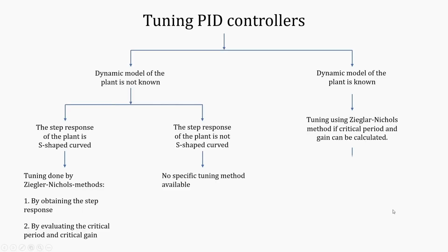If you have the transfer function, the first thing is that you can use the same method that you used for the closed loop case. The only thing is that since you have the transfer function now, you can find the value at which the oscillations will happen directly, using either root locus or the Routh-Hurwitz method. We will take an example and see how to do that.